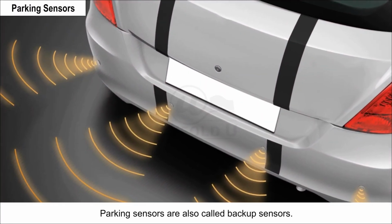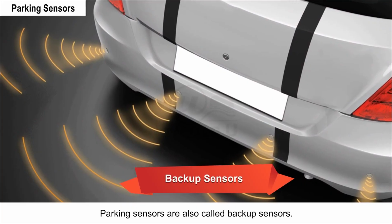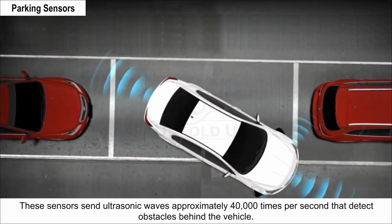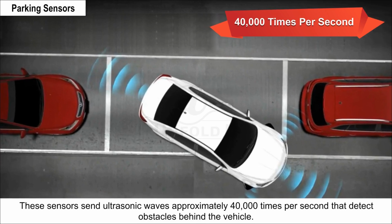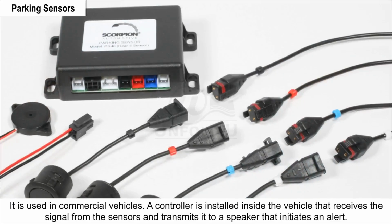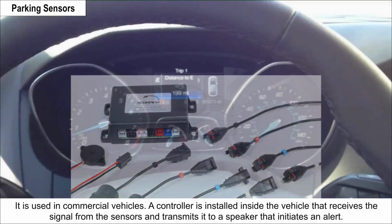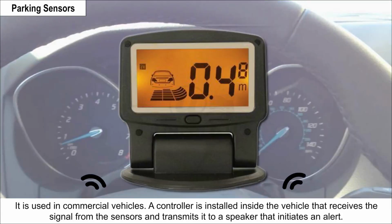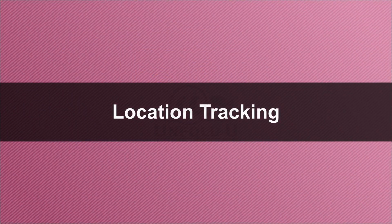Parking sensors. Parking sensors are also called backup sensors. These sensors send ultrasonic waves approximately 40,000 times per second that detect obstacles behind the vehicle. It is used in commercial vehicles. A controller is installed inside the vehicle that receives the signal from the sensors and transmits it to a speaker that initiates an alert.